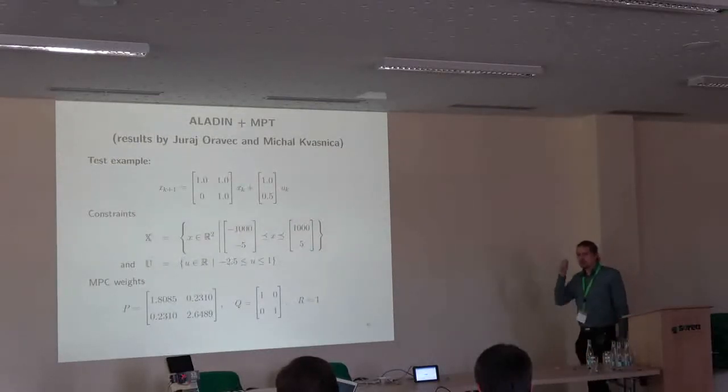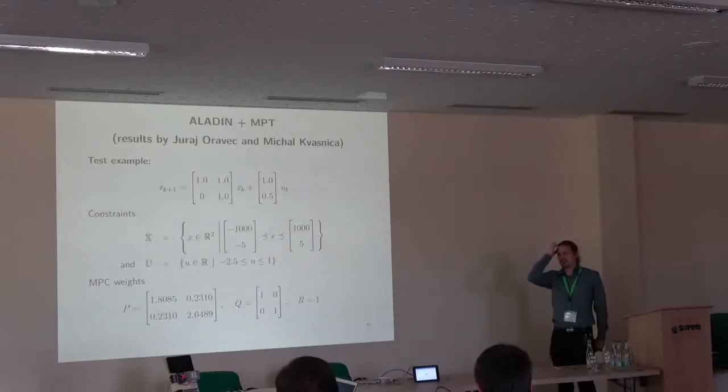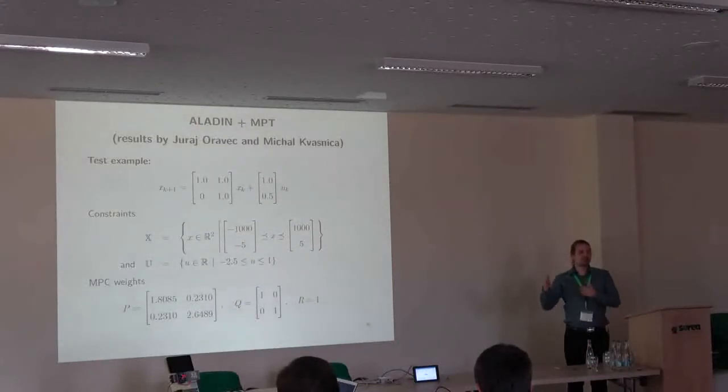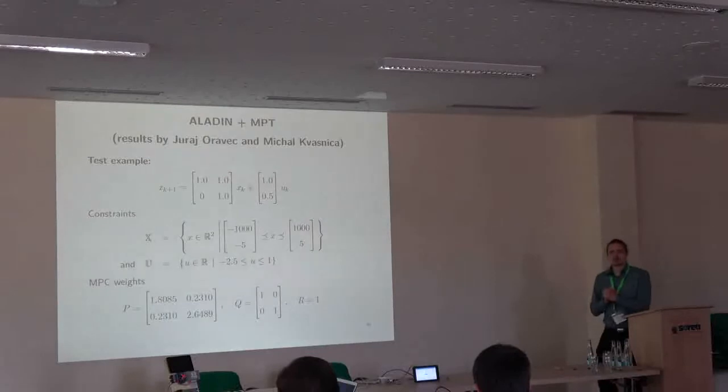What we can do in this case is overcome one of the big limitations of explicit MPC. In explicit MPC, the idea is that we enumerate all the regions that can come up if we take all the inequalities into account. That's pretty feasible for short horizons, since there are not so many possibilities about which constraints can become active, and there are very efficient solvers by Michal Kvasnica and co-workers, who have developed the so-called multiparametric toolbox, the MPT toolbox, which can compute these regions for small-scale linear quadratic MPC problems with inequality constraints.